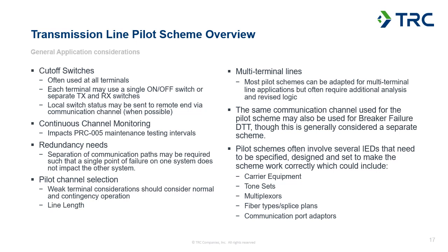We've also got some pilot channel selection requirements. So there might be some unique things you'd look into if you have a weak part of the system where you're applying the scheme, and some line length considerations like the SIR topic we discussed as part of the step distance scheme.